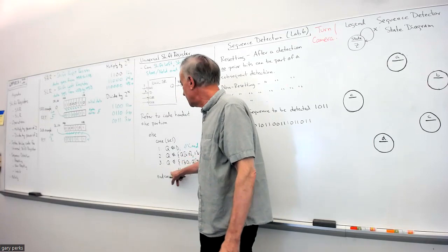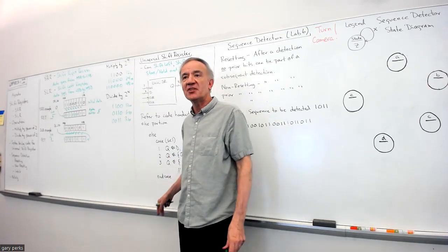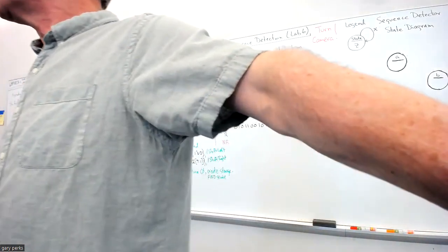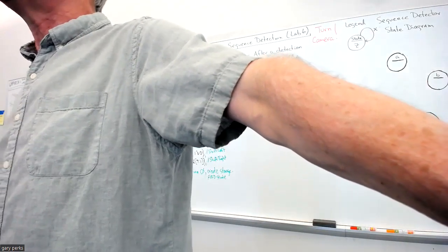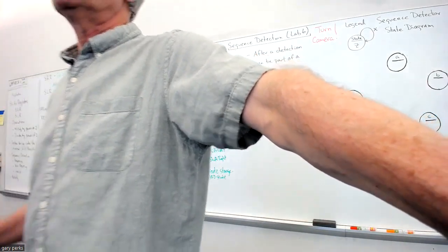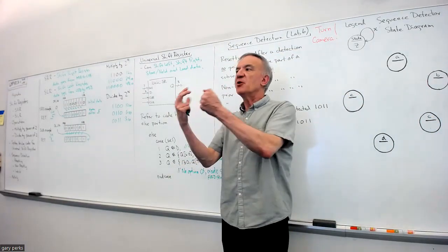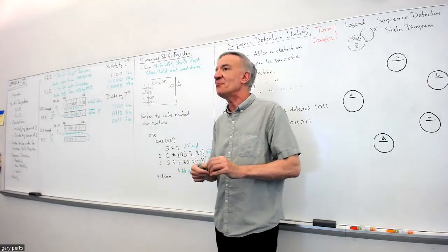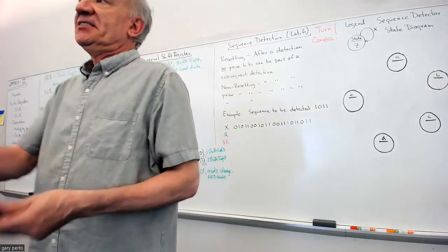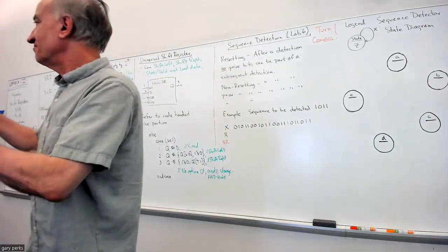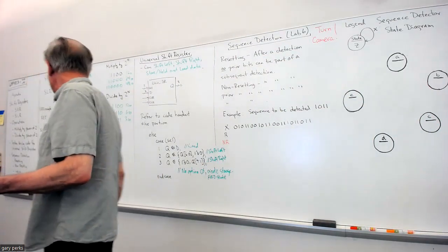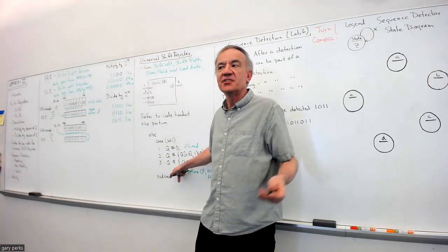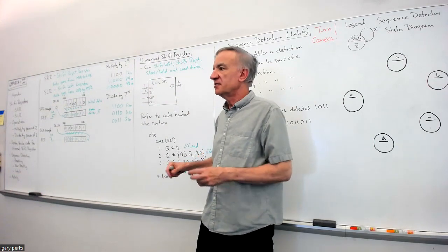Because if you did put something here and you assign Q to something, you might be changing Q to something that, depending on what the shift register is part of, what kind of system it's part of, might actually do more damage. It's better just to keep what you have, because you don't know when the default's going to happen. If you change it to something, whatever the shift register is connected up to might cause bigger problems. So it's better just to stay with what you got in this case. Okay, so you see, sometimes a default can be a hold, like we have here.